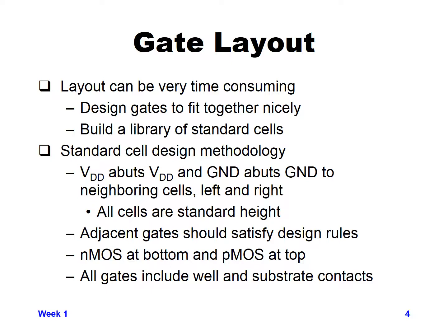But this requires all cells to have a standard height. So the distance between the VDD and ground, that's usually the outer top and bottom of the cell. You want to make sure that that height, that distance, is the same from cell to cell.